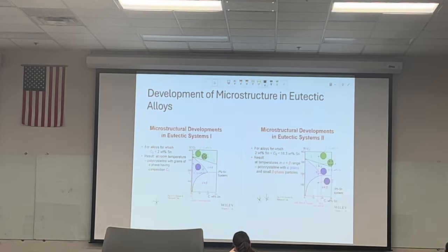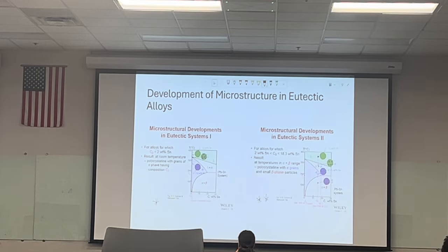as the alloy cools, we're starting off at this higher temperature again. As it cools from a liquid, it'll form a single phase solid solution, so in the alpha phase, or the alpha grains, and at this stage, it'll behave exactly like the low concentration alloy. It's crossing over into this L plus alpha. And pretty much as you go through these different phases, you end up with either liquid or solid forms of that material composition, essentially.